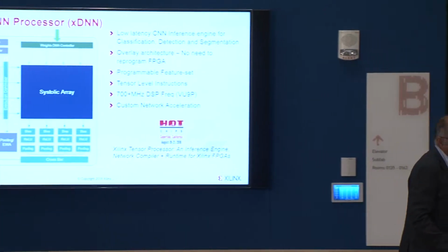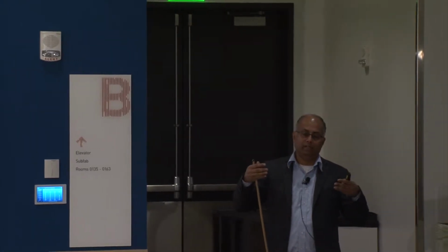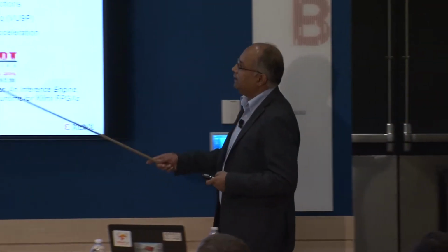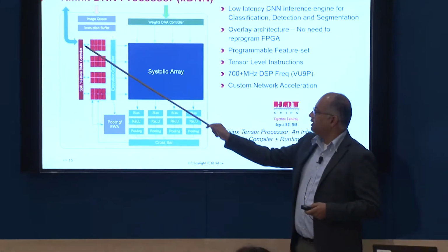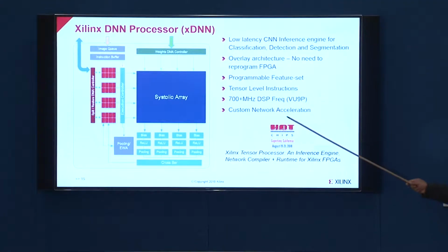Because typically, in the matrix multiplication problem that a lot of CNN algorithms get into, you have a lot of reuse on the activation, but the weights you can load in a slower manner. You load a chunk of weights and do a lot of operations on it, because your activations are reused quite a lot. And then you move it out to the DDR. So we don't assume everything will be in memory. If we don't have enough space, it will go to the DDR.